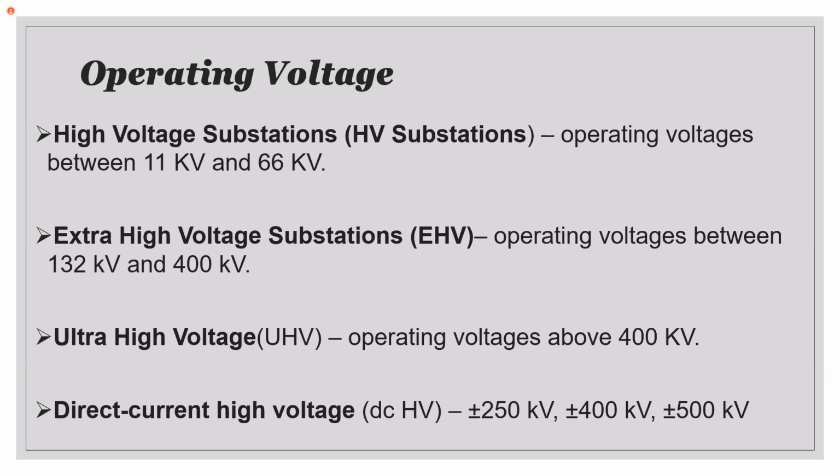Quick question, sir. Sorry to bring you back to the converter part though, sir, but my question is, as it relates to the frequency at which the voltage is produced, isn't it dictated by how many cycles per second of the generator itself, sir? And I'm speaking about the 60 cycles or the 50 cycles, depending upon the country, sir.